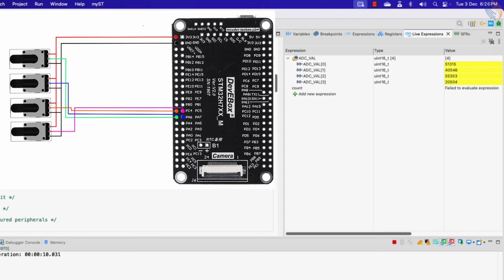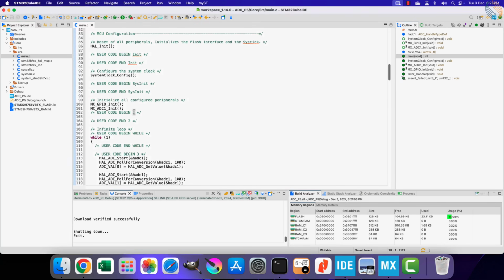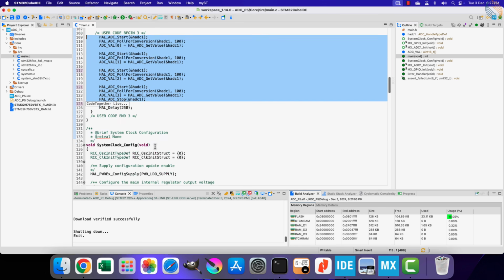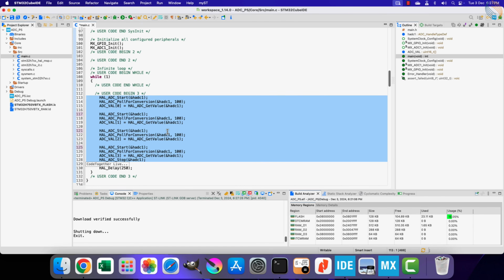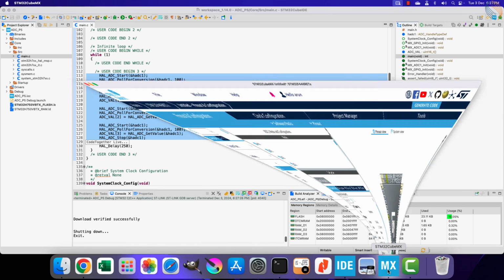So we were able to read multiple channels using the polling mode, and without the use of the DMA. Although if you see the code here, there is no point of doing it this way, since we have to read all the channels anyway, so why not simply use the DMA? We can stop the ADC after reading just 2 channels, so the rest 2 channels can be avoided, but if you want to get the data from the 3rd channel, you still need to read the first 2 channels.